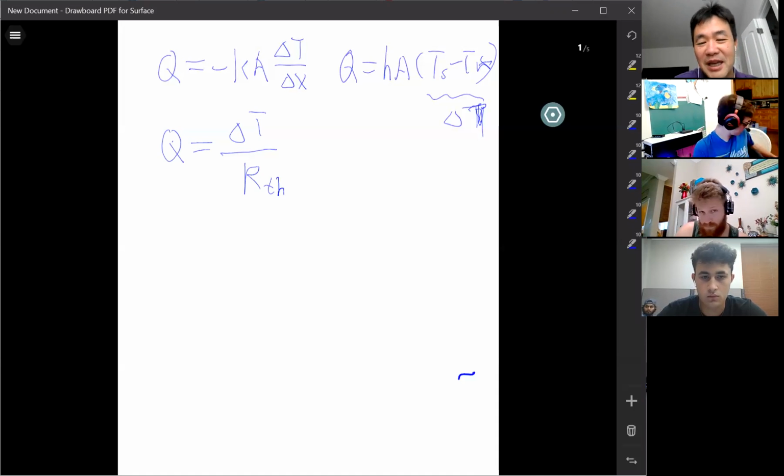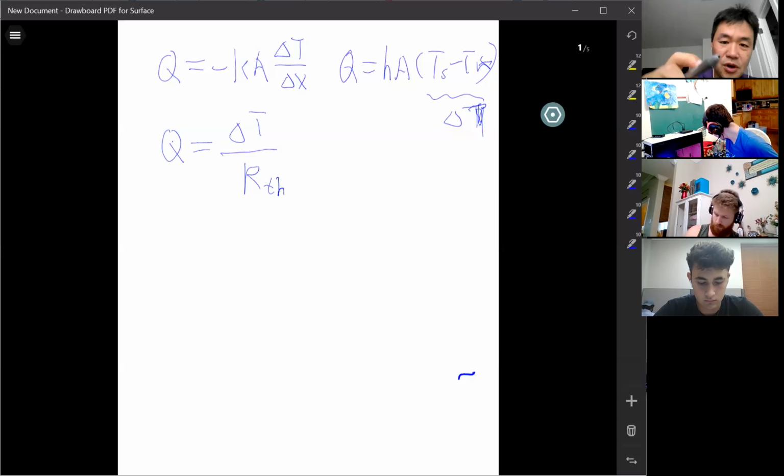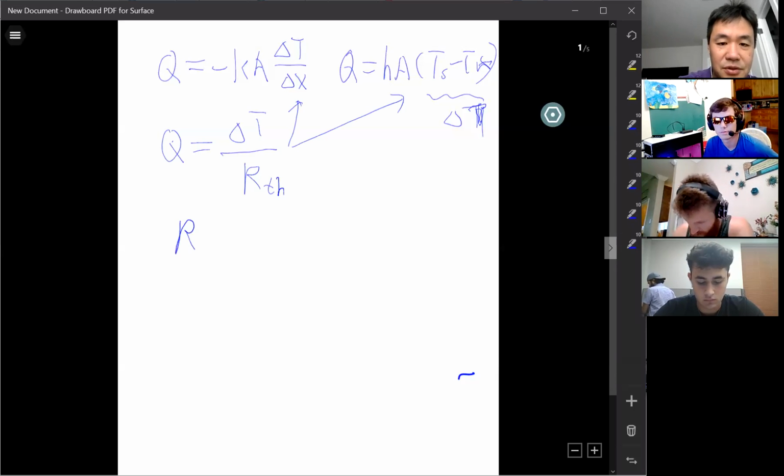If you can determine a thermal resistance explicitly, separately, then even if you write a calculation program on a computer, it's easy to do if you can just input the thermal resistance R. So the goal is to separately determine the thermal resistance. Look at these two equations. If you use the idea of thermal resistance, what does the thermal resistance equal in conduction? What?